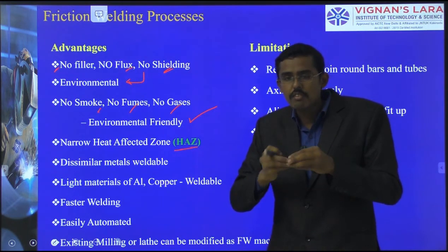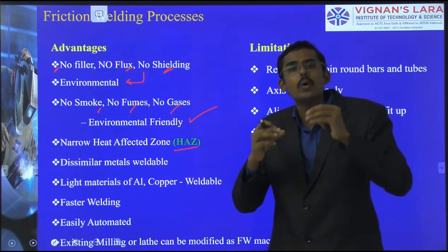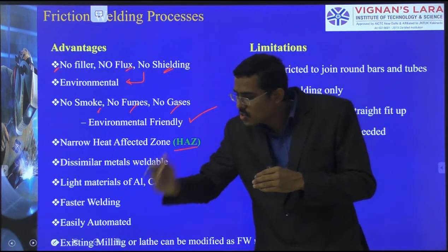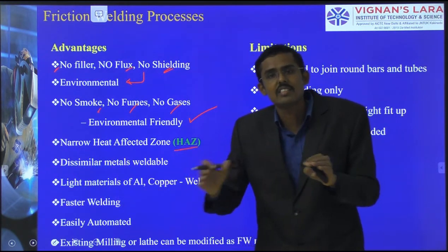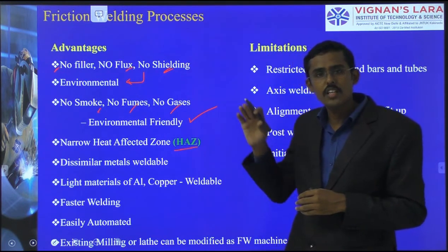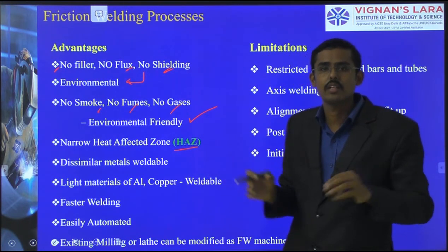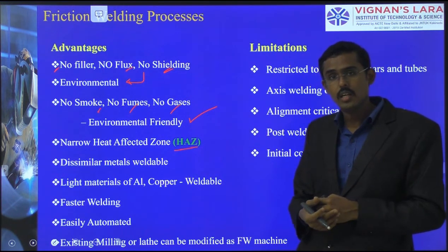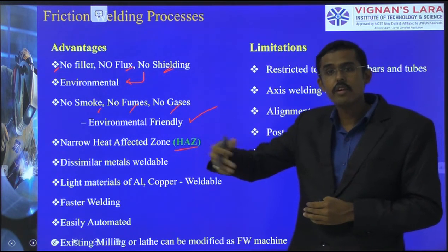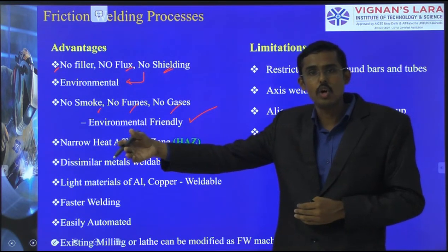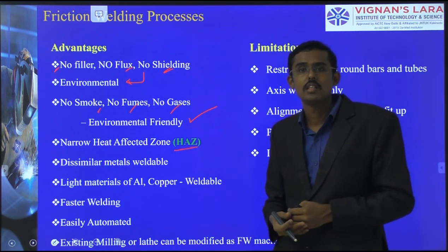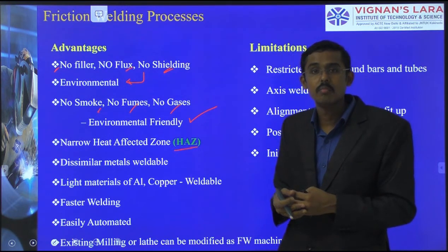And then at that time itself we give the pressure to make the weld joint. Therefore, the heat affected zones are very narrow. In solid state joining there is no heat affected zone, or very little. Therefore, there is an advantage. Heat affected zones may be brittle: if your heat is increased, obviously cooling will also be fast, so it forms martensite and brittleness will form.